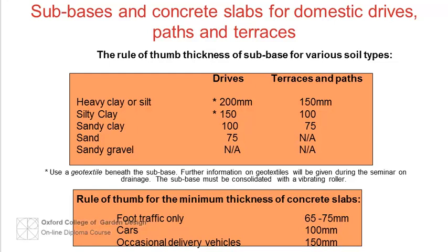The required thickness of subbase for various soil types is shown on the screen. On heavy clay soils, specify a geotextile layer beneath the subbase to prevent the clay working its way into the subbase should it become wet.